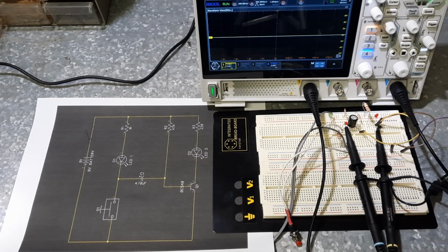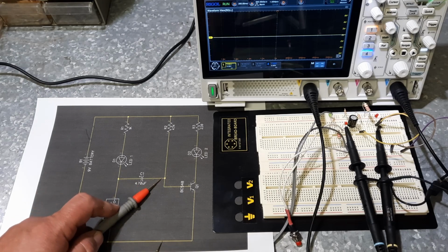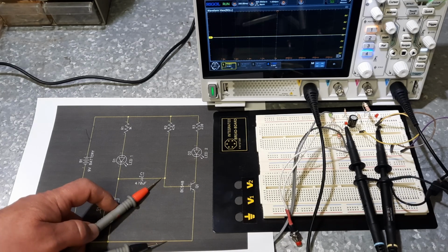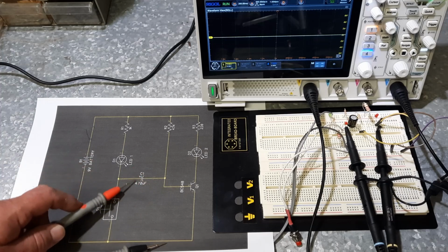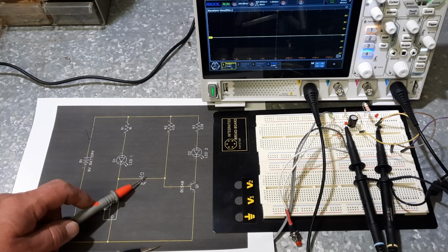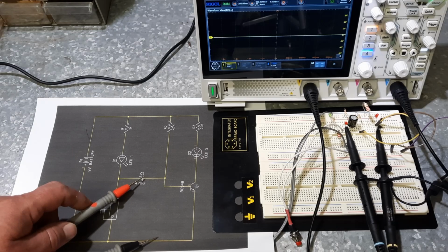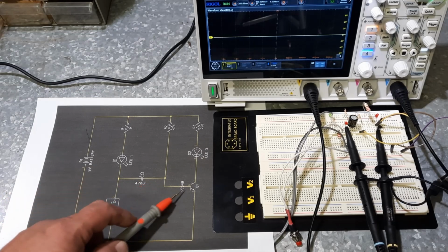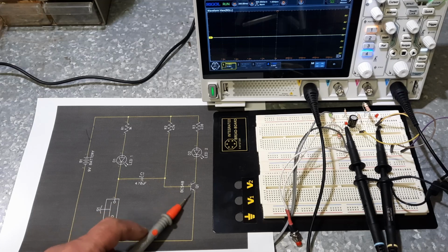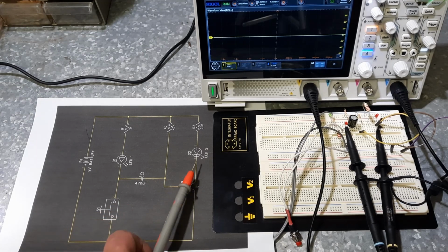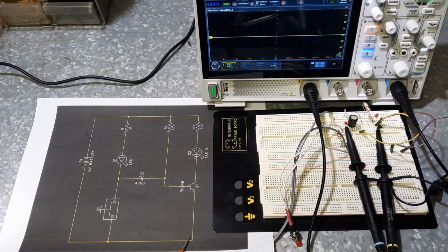So what else is going to happen in this circuit? Well, the second we push that, this plate here is going to look like a negative. So if we measured from here to here, we would have a negative voltage here, whatever this was charged at. So if we have a negative voltage here, that means that this transistor is going to go into its cutoff region straight away, which means all current flowing down here is going to stop. So this switch is now open.